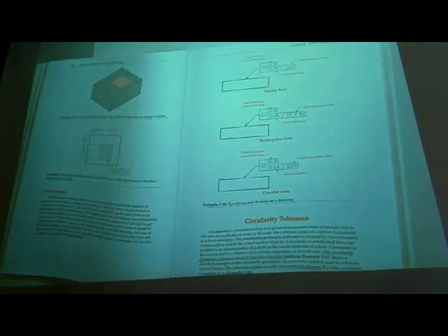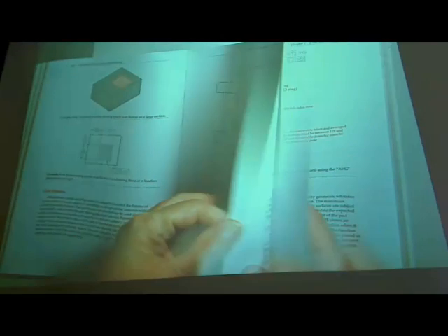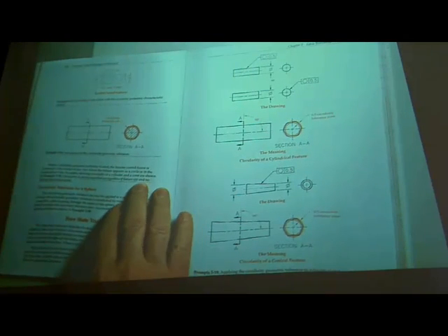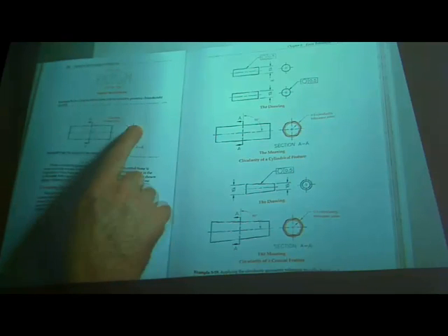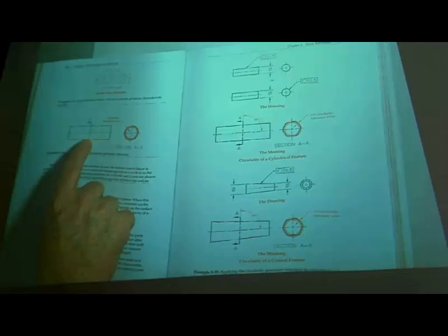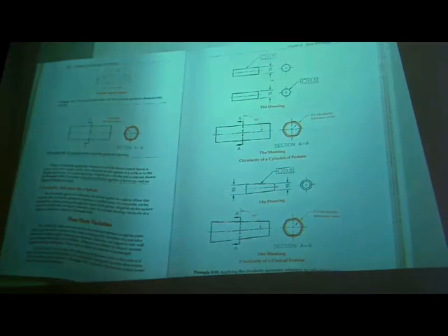You can use it either way, but when we're talking about circularity, it has to be less. Because we're checking the circularity, which is two parallel concentric circles, it creates a tiny, infinitely thin zone. It's in just that one area.